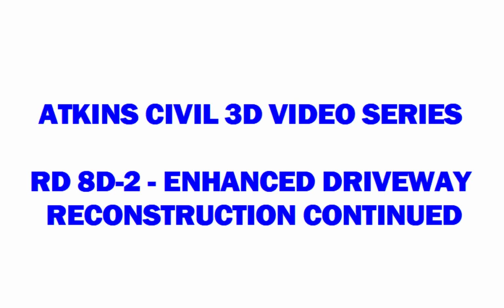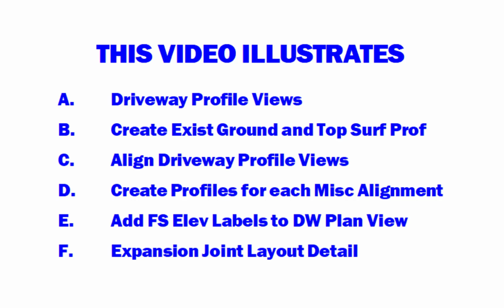Atkins Civil 3D video series, Road 8D-2, Enhanced Driveway Reconstruction continued. This video illustrates: A. Driveway profile views, B. Create existing ground and top surface profile, C. Align driveway profile views, D. Create profiles for each miscellaneous alignment, E. Add finished surface elevation labels to driveway plan view, and